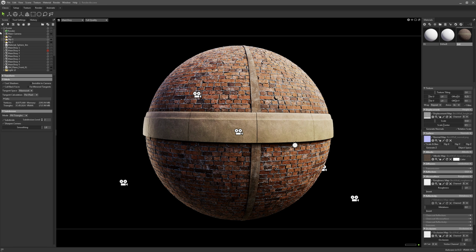So what happens is when you import this, you're going to see the name of the mesh and a plus icon. Click on that icon, go to the name of your actual mesh with this kind of blue cube, and go to the subdivision part. Set this to PN triangles and click on subdivide. Then increase the subdivision levels till you feel comfortable with the amount. Now be really careful, because this is really strong and can kill your computer.